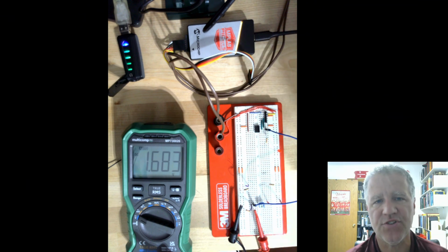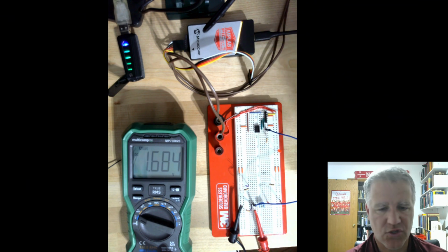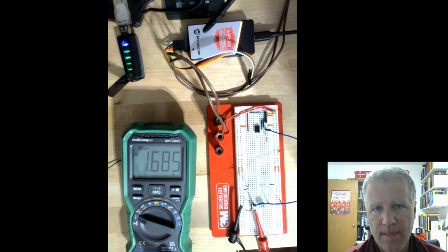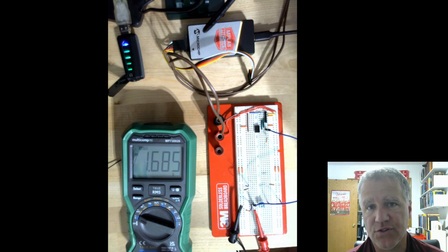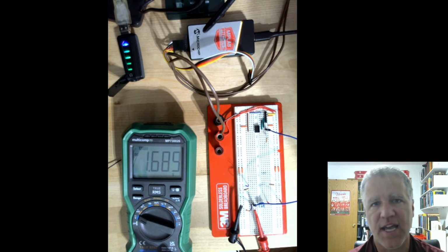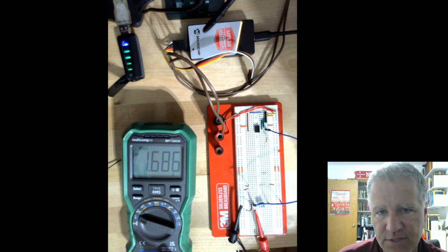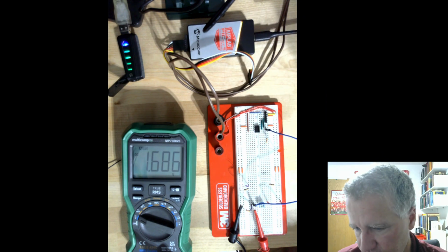This is a great feature that we didn't have in our more primitive baseline microcontroller, the 10F200, but now in this mid-range controller, still a very simple microcontroller, we have comparator capability, which can be very handy in the lab. And like I said at the board, you can sharpen this by doing some high-frequency noise reduction, incorporating an additional circuit where some capacitors shunt that high frequency to ground, or maybe across the two leads of the comparator. All right, so that's it for this lab.